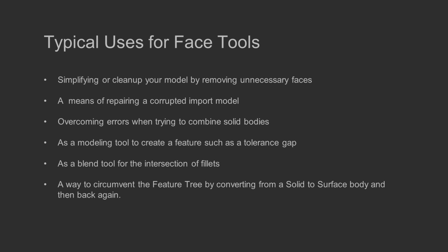And I've shown this in previous episodes where the delete face with patch is very useful for cleaning up setback points in fillets, and basically the blending between fillet edges coming together. And by being able to use the delete face option with the delete option where you're actually removing a face of the solid, you're able to convert your solid to surface body.